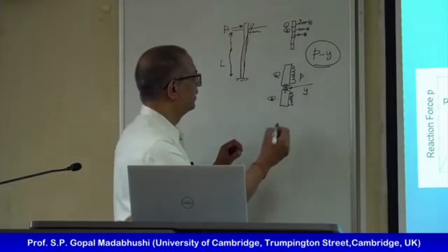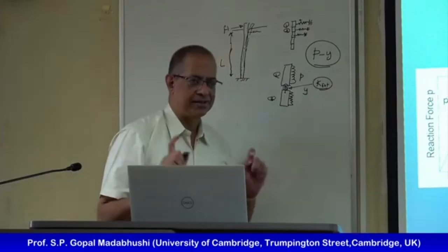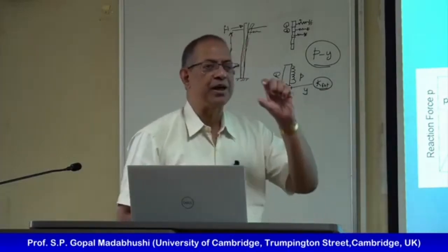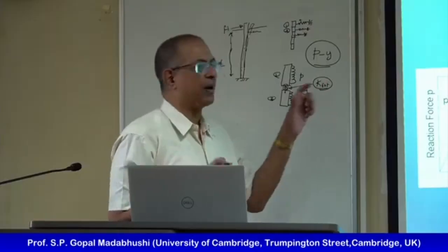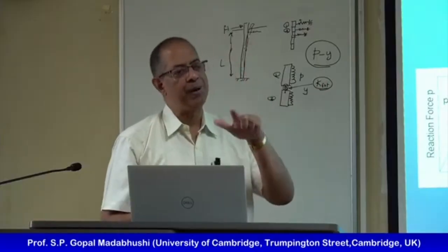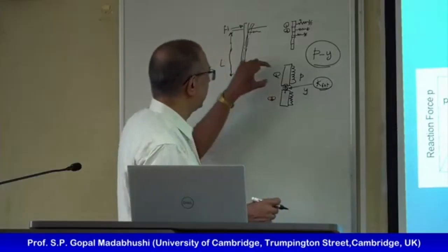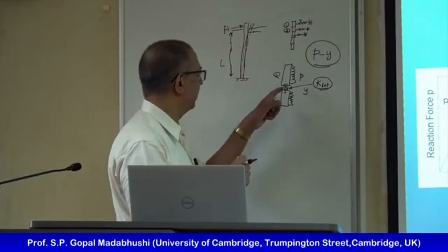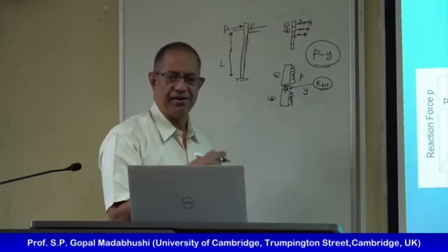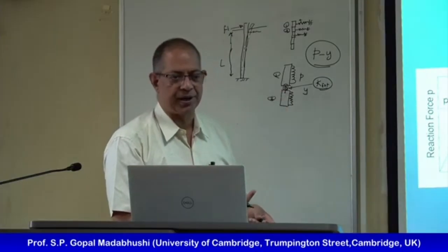So this rotational spring K is there because we took our pile and cut it into little elements, right? Obviously, the real pile is all one unit, so it'll have bending stiffness. So we can say, okay, I'll take each of these as rigid, and I'm mimicking the bending stiffness as the rotational stiffness of the spring.